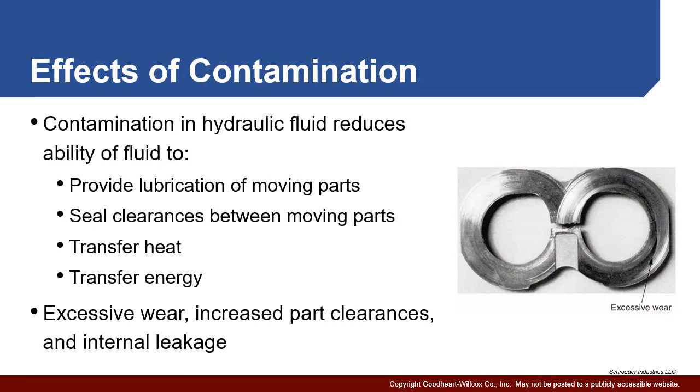So why is it so important? Well, as I said, about 75% of all failures are attached to it. But why do those failures occur? Keep in mind what contamination does in hydraulic fluid is it reduces the fluid's ability to do a number of key things. For example, provide lubrication.